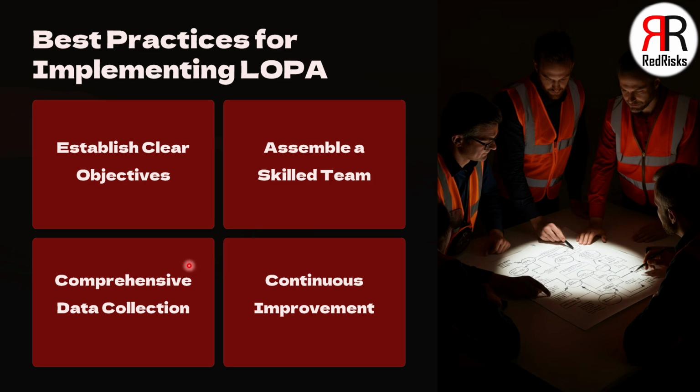We can gather detailed information on equipment, processes, and past incidents to establish a solid foundation for the LOPA analysis. Continuous improvement is of course important, and regular review and update of LOPA to account for changes in processes, equipment, or regulations to ensure that they have an ongoing safety performance mode built in.